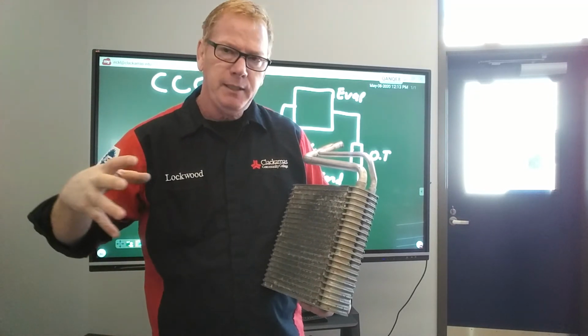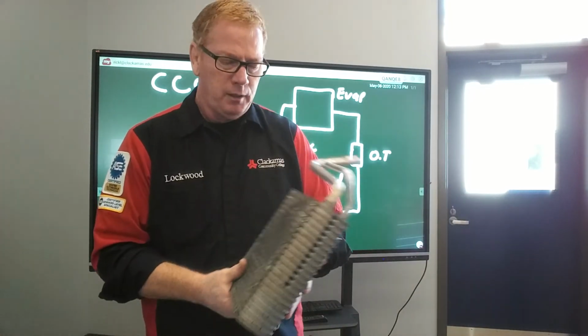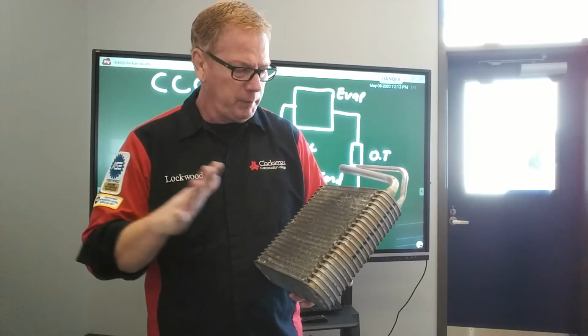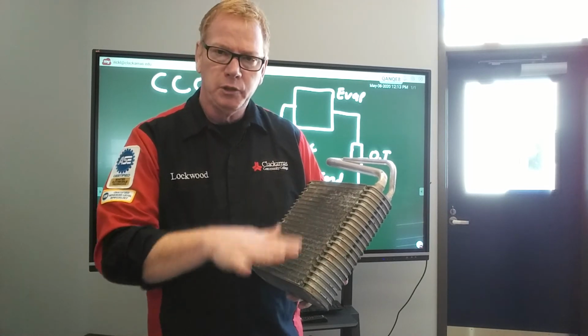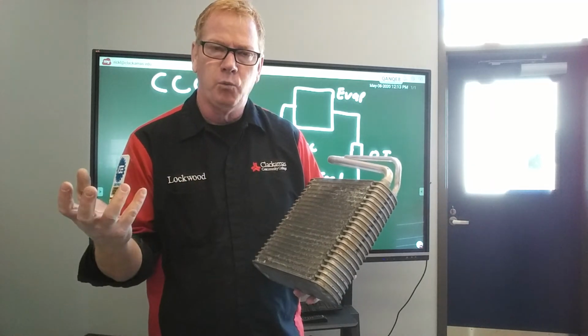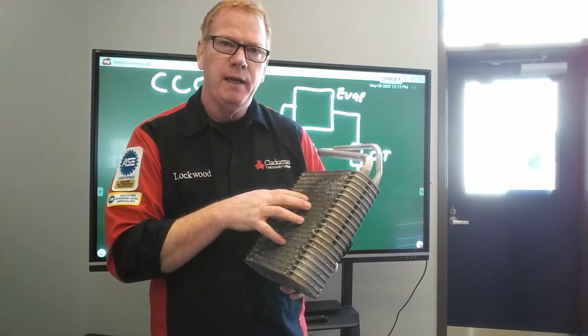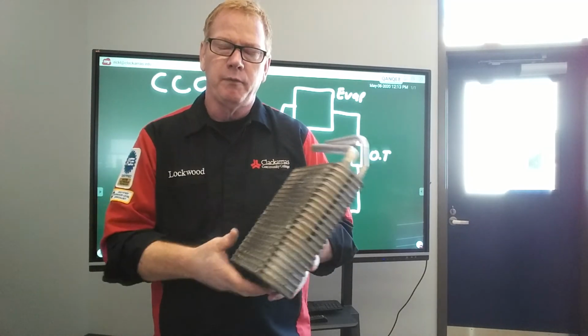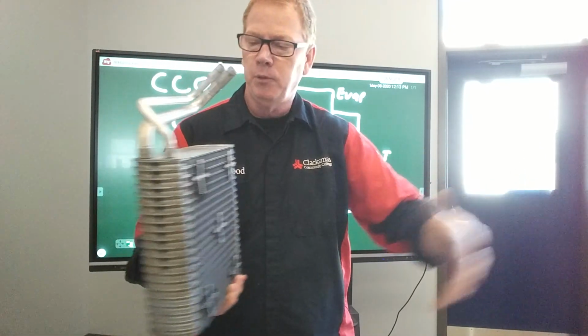Either way, we're going to take that air, we're going to push it through here and pass through. So the ambient air itself will make contact with all of the fins that have transferred that cooler temperature to the fins, and we're going to take a warmer air and run it across it. That warmer air going across this, that heat will be absorbed into the refrigerant and carried out, and the cooler air that we blew across it comes out the other side, and that will be coming out the vent, the floor, or the defrost, or a combination thereof.